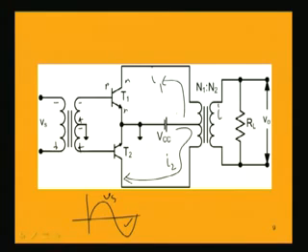So, ignoring the transistor drop, which is very negligible, the maximum collector current can go up to VCC by RL dash. RL transferred to this primary side will be RL dash, which is N square into RL, N being the turns ratio between primary and secondary winding.